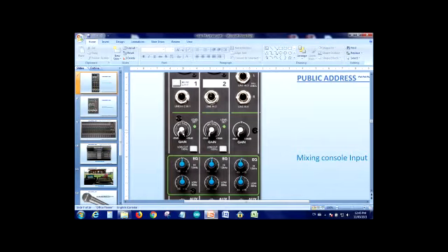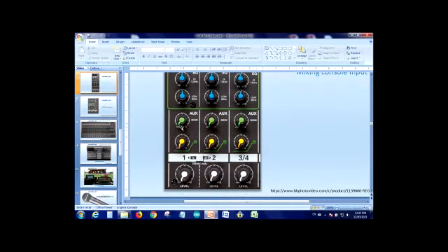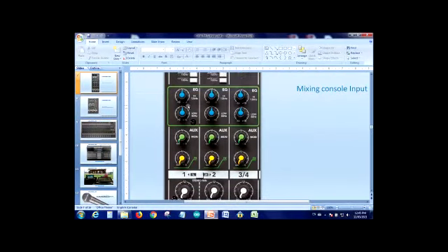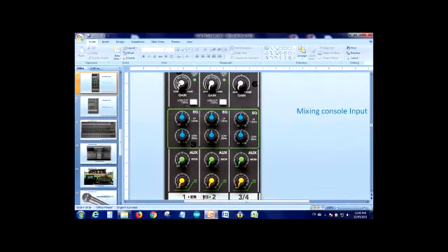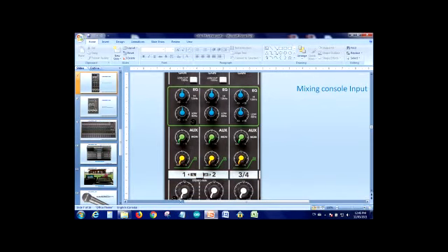That's the first stage of the amplification of the signal. You are adjusting with the gain knob, or potentiometer, the gain of the incoming signal, so you're going to have a comfortable way of maneuvering this main volume for this whole strip. So you're setting up the levels for the comfort of this volume control that is servicing this whole strip.